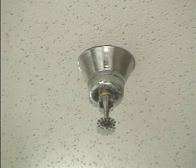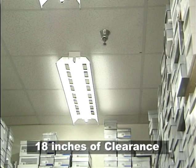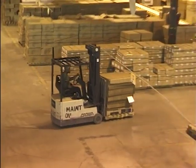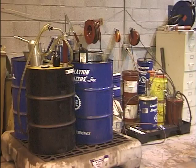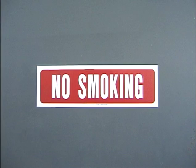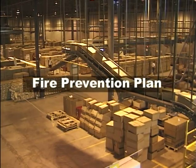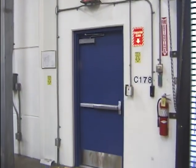The same applies to automatic fire sprinklers. They must have at least 18 inches of clearance to function properly in the event of a fire. It's not just good housekeeping, it's the law. It's everyone's job to help keep the work area clutter-free and safe from other fire hazards, such as improperly used or stored chemicals, which we will cover in a couple of minutes. Also, remember that smoking is only allowed in specially designated break areas. No exceptions. Your company has a written fire prevention plan, and it's critical that you know the actions you're expected to take in the event of a fire.